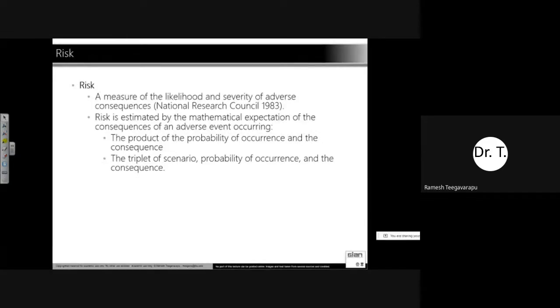So these days, there is more assessment of the risk because risk is something which every agency maintaining the reservoirs or dams, one and the same, is trying to understand, whether there are higher risk dams or lower risk dams, and how do we estimate the risk, because there are both climatic factors and non-climatic factors, and the probability of occurrence of a specific catastrophic event, and then of course the amount of damage a particular event will cause. That's what we call consequence. So therefore, nowadays we are considering the triplet scenario: probability of occurrence, the consequence, and then of course the estimates of the damage.